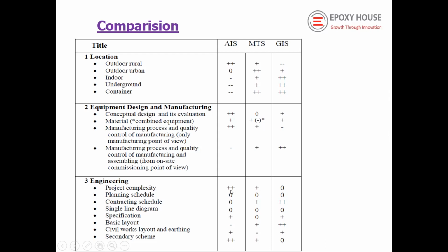In a project, the individual components are kept in series one by one, so the project is not complicated. It is all material, but the problem is the engineering point. It has to be pre-planned very meticulously to have all the equipment. But in case of the GIS, all components will come together, so it is easier. Contract schedule can be reduced. That's why GIS is better in terms of planning the substation in a short time.